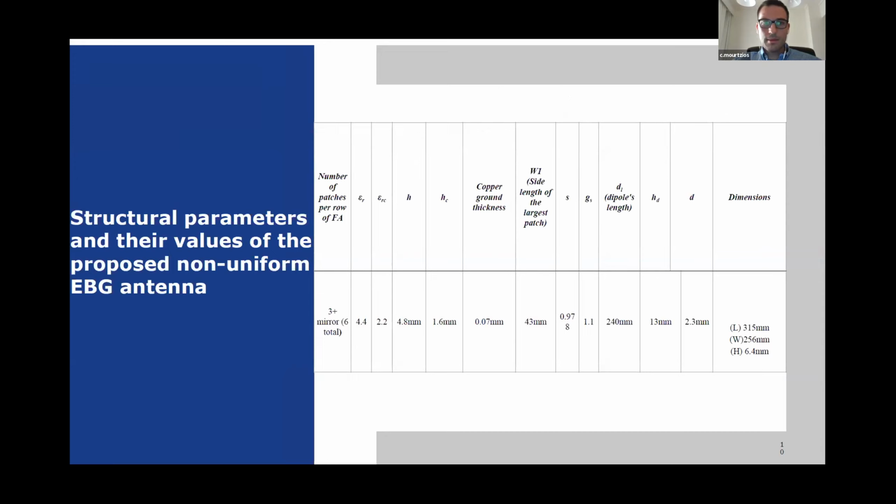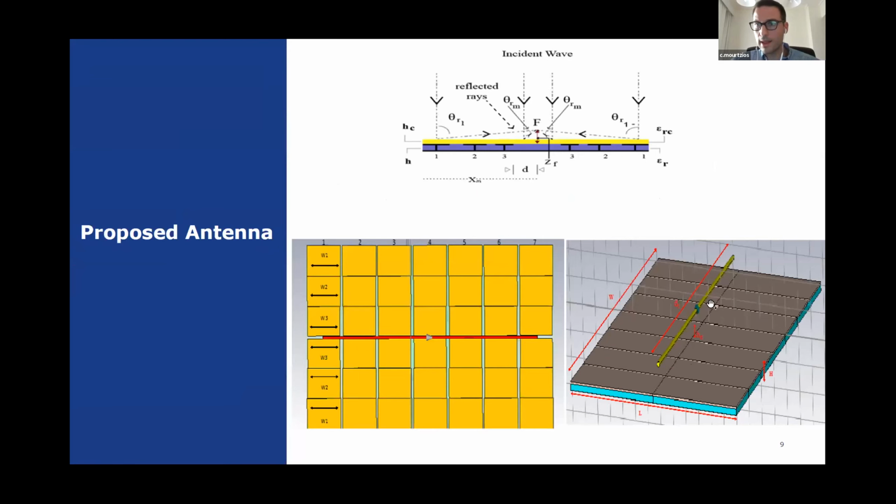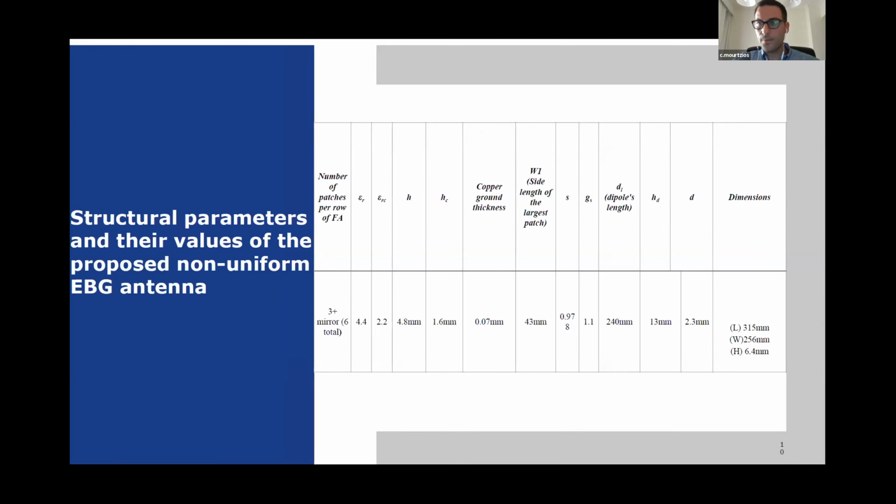These are the structural parameters and their values of the final proposed design. All these parameters were modified via iterative simulations with the intent to maximize VOC at the open terminals of the dipole, treating the whole device as a passive receiving element with incident waves on it of circular polarized waves of field intensity of 1 volt per meter.